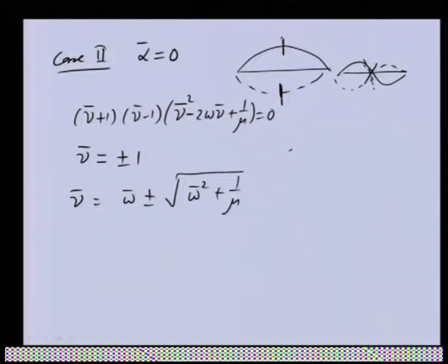You can see this is similar to the previous one, in which earlier the critical speed was the whirl frequency like this, but in this particular case the whirl frequency now depends upon the spin speed of the shaft. So, if we try to plot this,